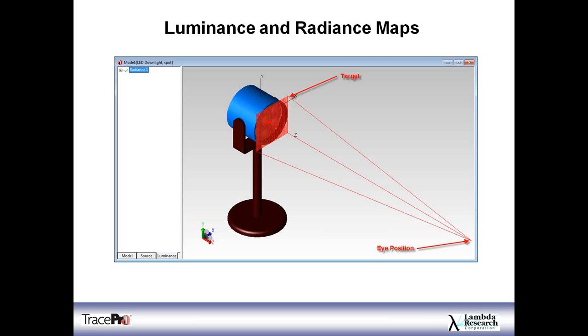And then we have a question regarding applying a filter on the source and then checking the real color, or the true color. You could do that, yes. Say we had this example here, we could tint this front lens. We could apply a surface property that has color-dependent transmission. So we're actually defining a filter for that lens, and you could run that ray trace, and then look at true color or CIE coordinates for that and see the effects of applying that filter. So I'd apply the filter as a surface property to the lens.